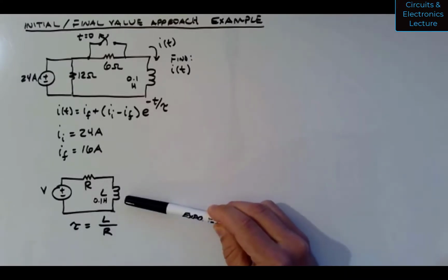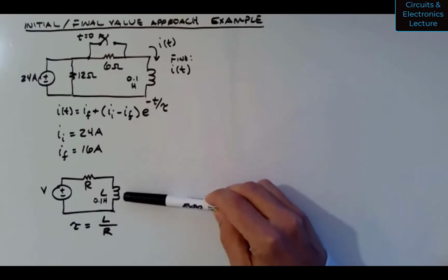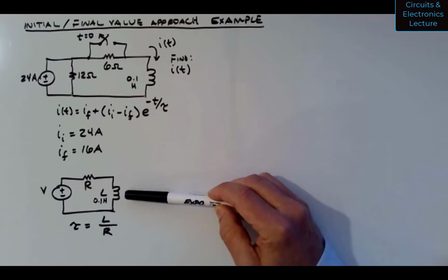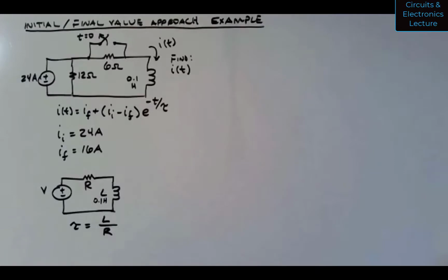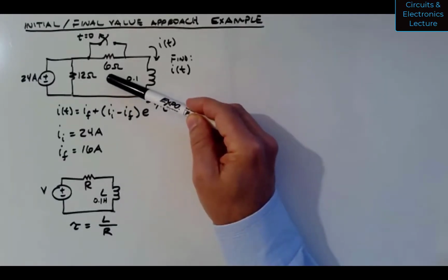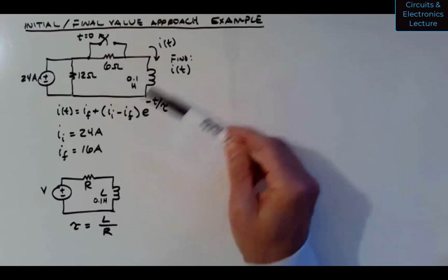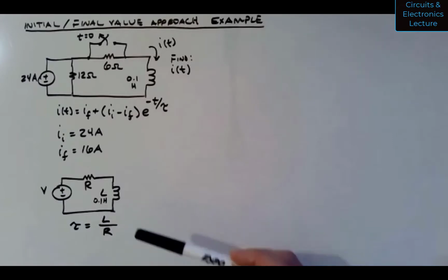And we didn't work this problem, but I told you, and I showed you on a slide last time, that if you did work this circuit at the bottom left using KCL, KVL, and differential equations, you would find out that the response has a time constant of L over R, okay? But we don't really know which R to use in the circuit above. We have 2 resistors in the circuit connected to an inductor, so this doesn't help us too much, well, yet.